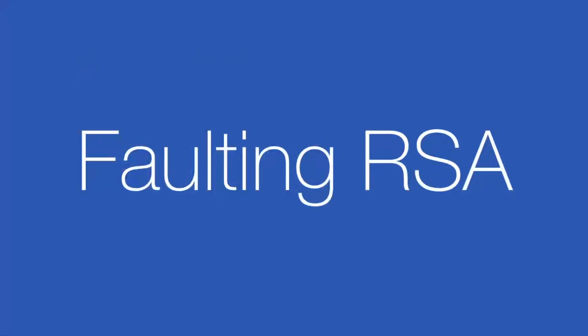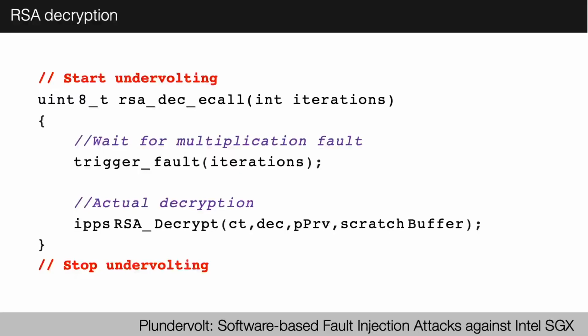Our research up until this point had just been inducing faults into multiplications, and we believed that we should be able to leverage that into an attack. So we decided to go after RSA, and remember, this is all happening in calculations inside SGX. We started off by waiting for the multiplication faults, so waiting to get an error in a multiplication before doing a decryption, and then seeing if that decryption would also fault.